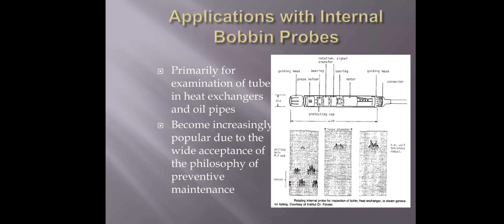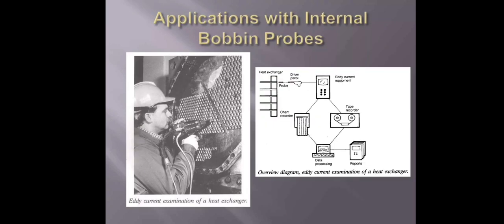Application with internal bobbin probes. Primarily for examination of tubes in heat exchangers or oil pipes. Becoming increasingly popular due to the wide acceptance of the philosophy of preventive maintenance. This picture shows the eddy current testing of a heat exchanger.